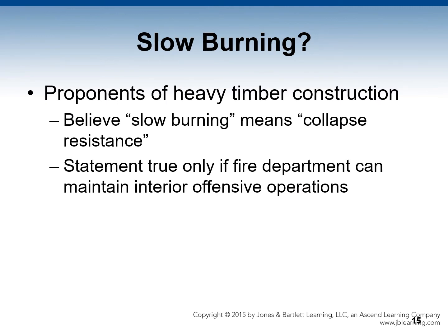Slow burning, that is a myth. Proponents of heavy timber construction believe that slow burning means collapse resistance. They certainly are not the same. This statement is true only if the fire department can maintain interior offensive operations. That depends on how quickly the fire department gets there, basically.